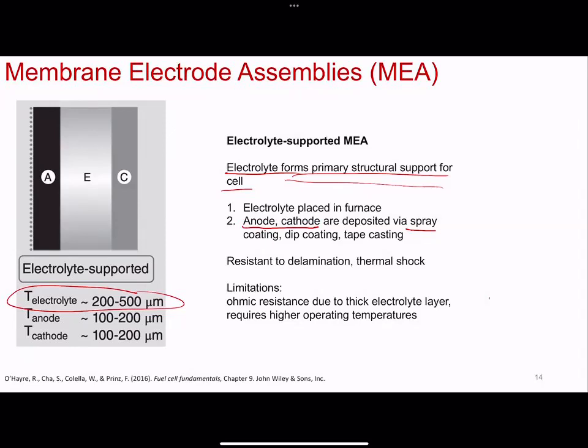That depends. So spray coating is pretty fast because you just need to make your solution, you hook up a hose and you spray paint, but then you have a solvent problem. Because typically the ceramics, you disperse them in, let's say, alcohol, even ethanol, say, okay, that's great. But now once you spray, you have to evaporate off the ethanol. So you kind of need a little bit of gentle heat to get that going. So you add like a step.